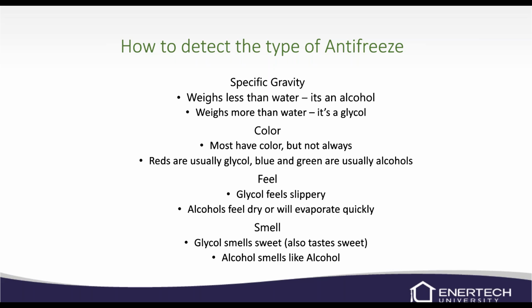The best way to know if you can't tell by feel or smell or what have you is to use a hydrometer or a refractometer. It'll tell you. Usually you can tell pretty quickly if it's an alcohol or a glycol. Smell and feel usually work probably the best for me on figuring out what's in it without a hydrometer.